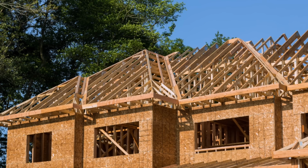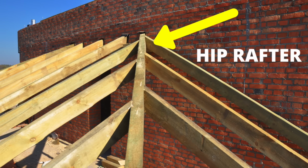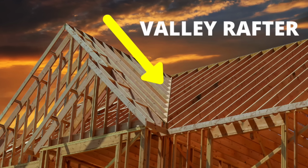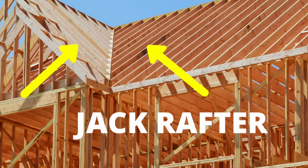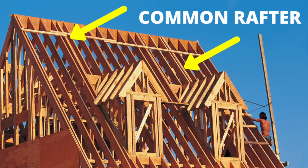In houses with contoured roofs, the framing gets more complicated. To create an outside corner, a hip rafter descends from the ridge to the corner of a wall. To create an inside corner, a valley rafter does the same thing. So these roof contours are simply called hips and valleys. Shorter rafters that meet a hip or valley are called jack rafters, but rafters that go all the way to the ridge are called common rafters.